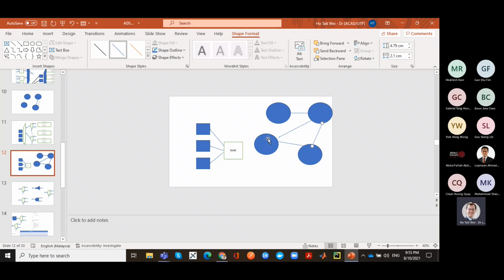This is a particular evolution, a particular sequence of states of modes, right? And this sequence of states of modes is basically, if you're in this state, if these values are holding a certain state, these values will be fed back into the RAM, into the address as an input. This RAM will decide, okay, go to this next state, right? Then it will load this next state value here. And when you want to decide the next state, these values will go back into the RAM as part of the address because that's the input, and you can decide to go into this state and so on, right?